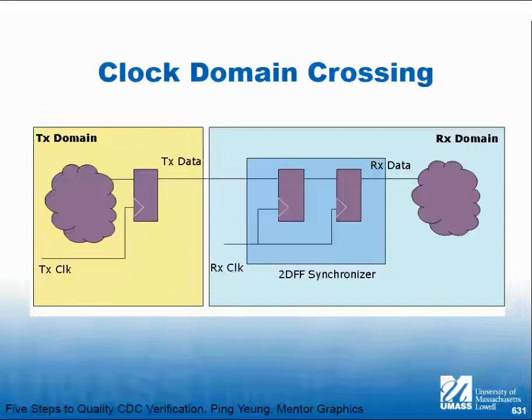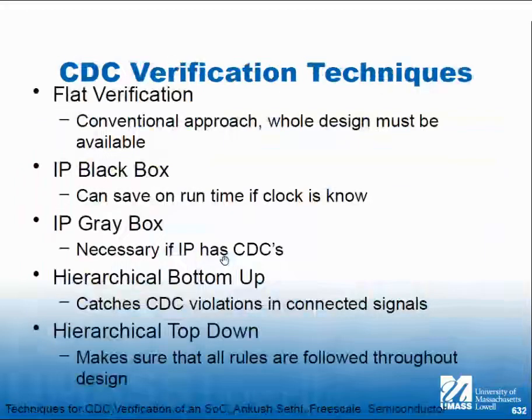But anyway, you should be able to do this without asking ChatGPT, right? So the receiving clock domain has 2 flip-flops. And a lot of times in ASIC libraries, there's a cell with 2 flip-flops in it. So how do you do it?